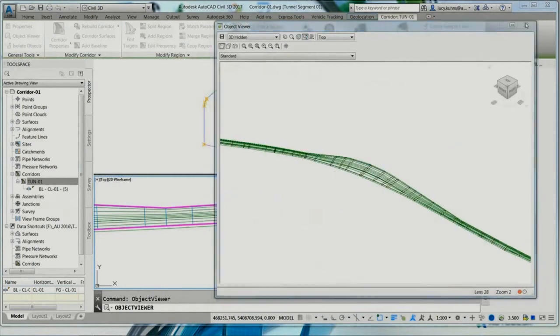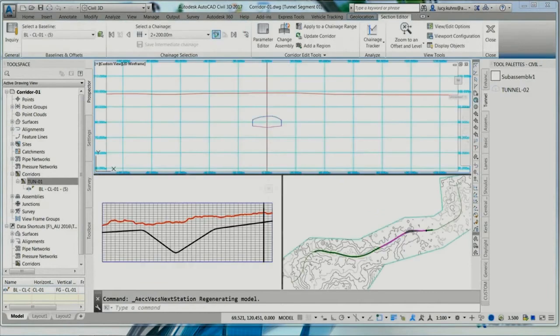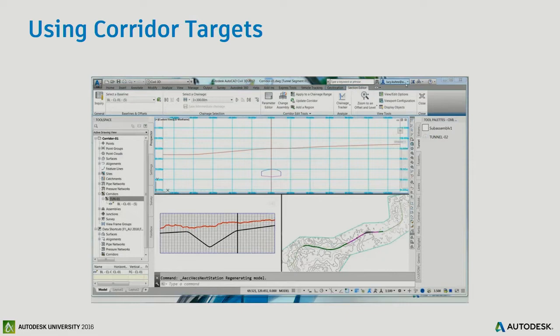And I did that just with the one cross-section, and you can see it go wide in the cross-section, goes wider, wider, wider, and now it goes narrower, and it goes deeper and deeper as I drop down with the profile. So we have the plan, the profile, and the cross-section view. That's a nice thing about civil. If you're not into civil engineering, these are very valuable layouts that show you the plan view, what's happening as it goes up and down, and then this as the cross-section.